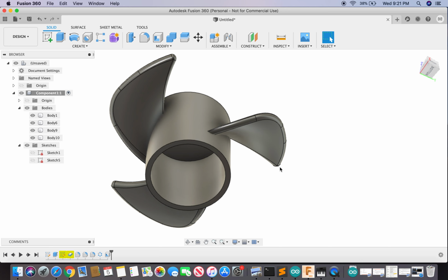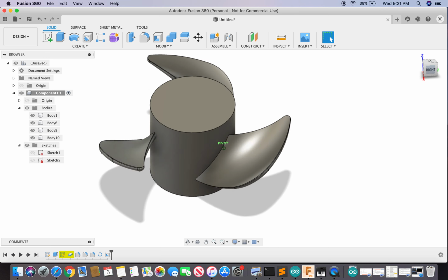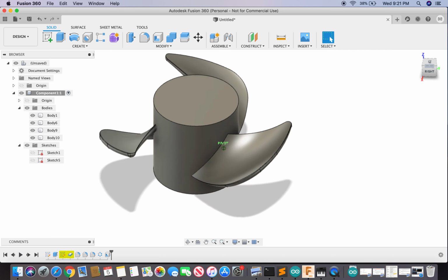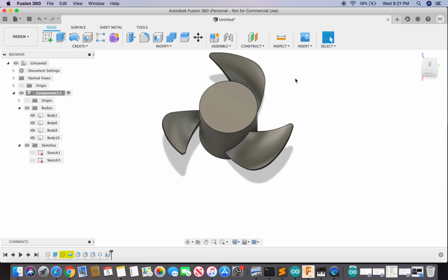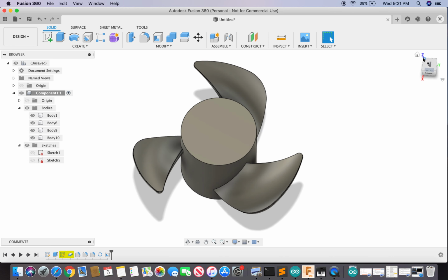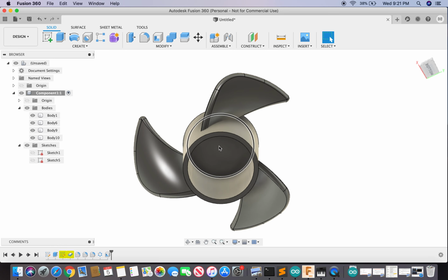Okay, so let's say this inner circle is just overlapping. That's just the way that it is. Anyway, I'm not gonna just make it bigger. You can play around with that. Like if the motor diameter is 50, make the diameter of this inner circle maybe 50.5.